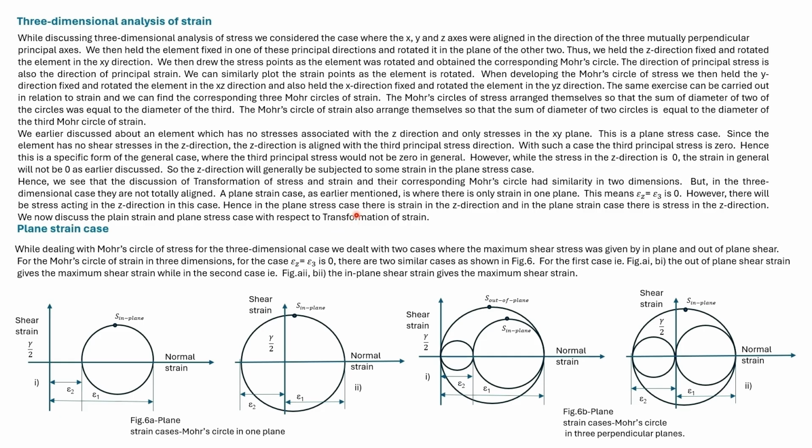For Mohr circle of stress for the three-dimensional case, we dealt with two different types of cases. In one case, the absolute maximum shear stress was given by the maximum out-of-plane shear stress, while in the other case, the absolute maximum shear stress was given by the maximum in-plane shear stress.